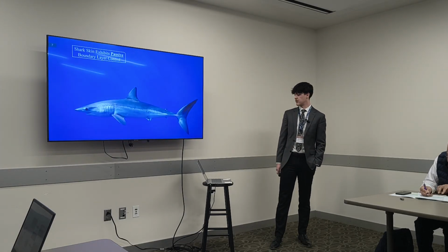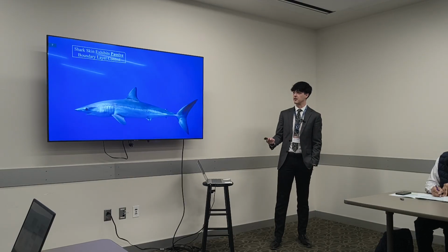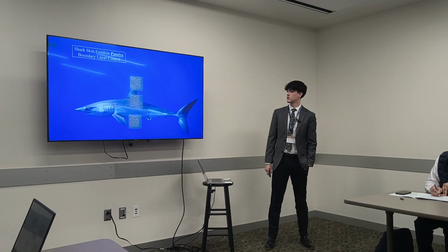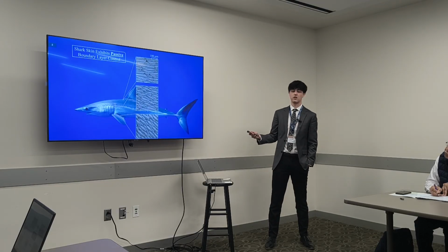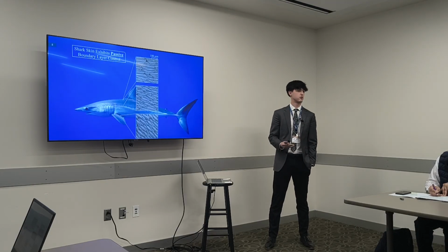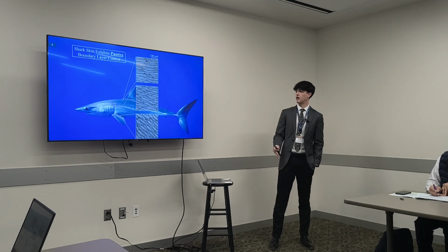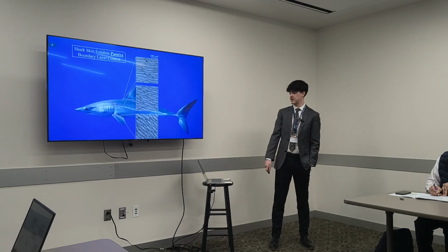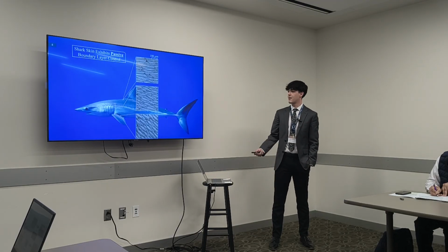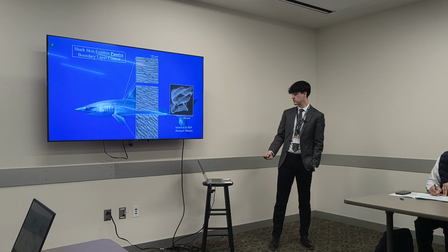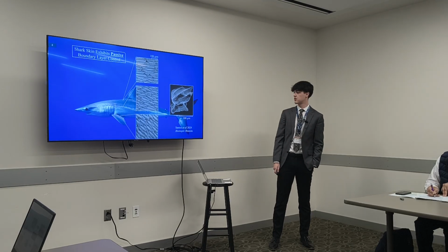So one example in creation is the shark skin. This exhibits passive boundary layer control within what are called shark denticles. And so this control, passive boundary layer control, basically means that it controls that flow separation without using any other external energy. And so this automatically happens because of these 100 micron shark denticles pictured here. And so these images were from a study from Santos and others.